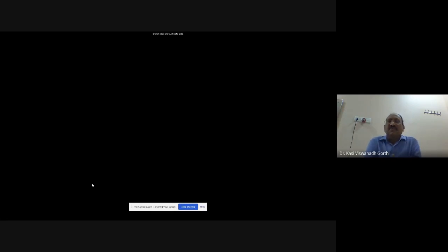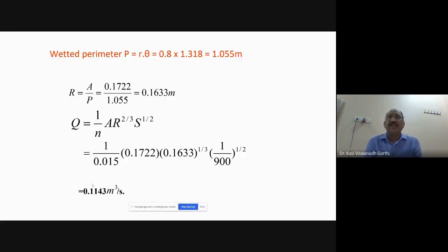So this finishes the working of some of the problems. We tried to analyze the uniform flow with different shaped channel sections like rectangular, trapezoidal, or circular channel sections, by making use of either Chezy's formula or Manning's formula, and various varieties of problems: calculating the longitudinal slope, the mean velocity, the discharge, and the depth of flow by making use of the trial and error procedure. So we tried to cover all varieties of problems in application of uniform flow in open channels. So this is the analysis of the uniform flow in open channels. I request all of you, please work out these problems once again.